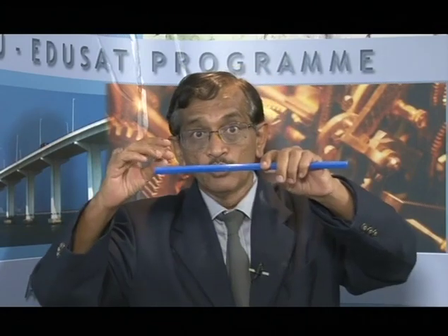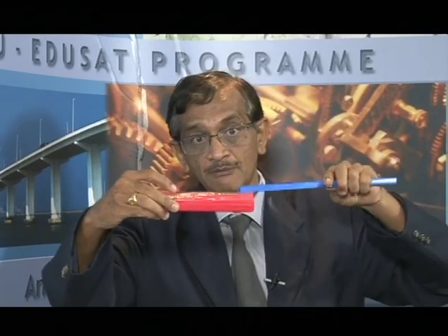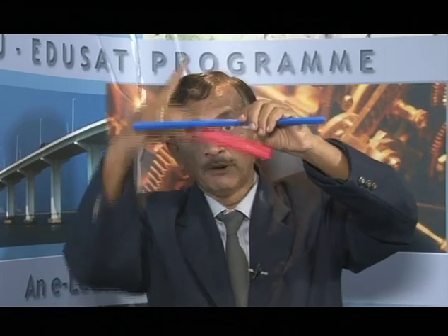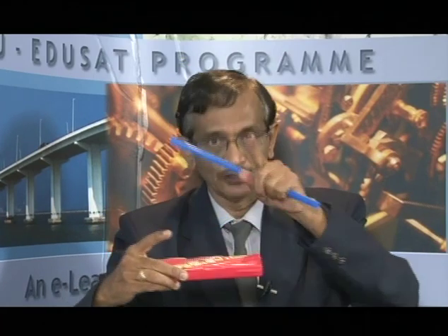It means I am going to measure from the gauge, but sometimes they will ask you to give it in terms of absolute pressure. Then I will measure from the zero, absolute zero. Gauge pressure can be positive or negative, but absolute pressure can never be negative. It's always positive, right? So in that case, the atmospheric pressure is a very important one.